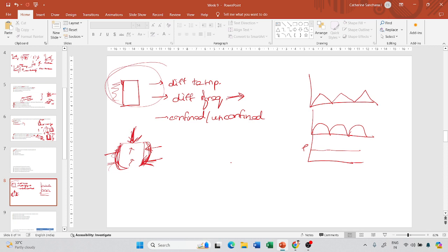Certain studies have said that if I'm trying to measure the response of the material at this point, so let us consider this is my pavement and I'm trying to measure the stress or strain response at this point. There is a vehicle passing from here to here. What will happen when your vehicle is here? The strain on the material is going to be less. As the vehicle comes closer and closer, the strain exerted at this point is going to be higher, right?